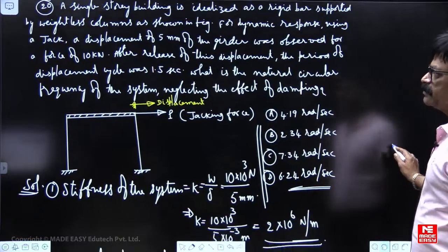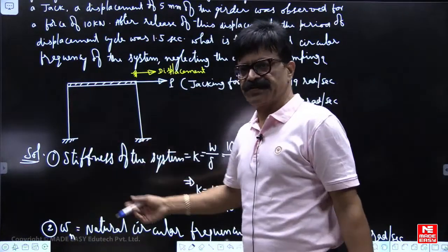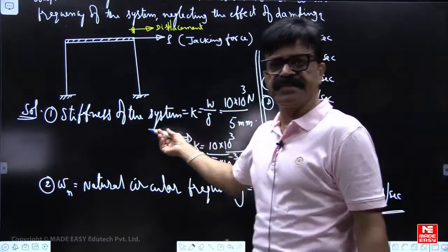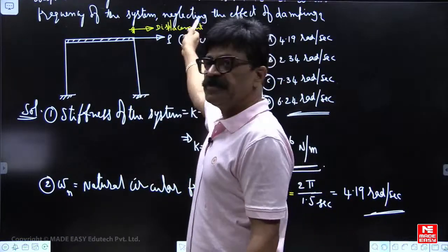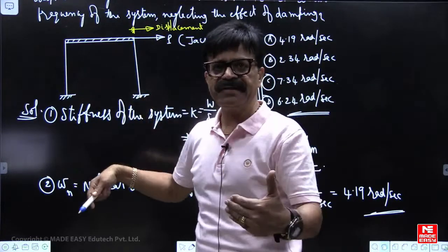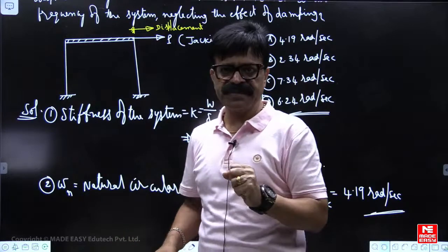So like this, in the GATE they don't ask you beyond this one. If they ask you what is the stiffness of the system, how much load you have applied, how much it displaced, load by displacement will give you stiffness of the system.